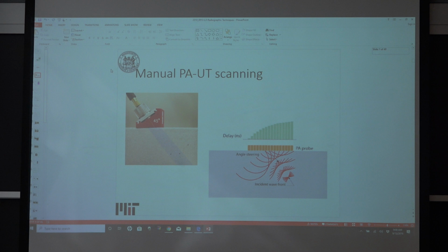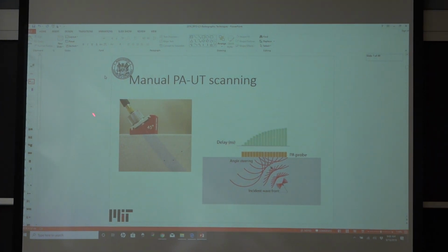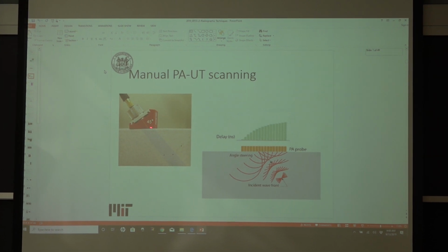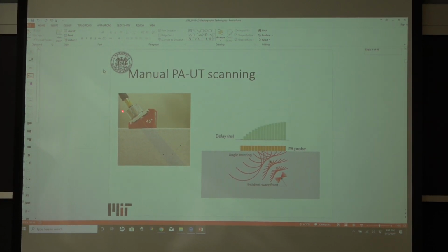That previous slide was for a longitudinal scan. The other type of scan would be a shear scan at an angle. What you're seeing here is a 45-degree wedge, which means your transducer is interrogating through the sample at an angle. If you looked at that schematically, this would be the area of interest. If this were your titanium or aluminum alloy, what you'd be seeing in this wavefront would be the scatter or the attenuation of the various acoustic waves as it goes through the thickness.